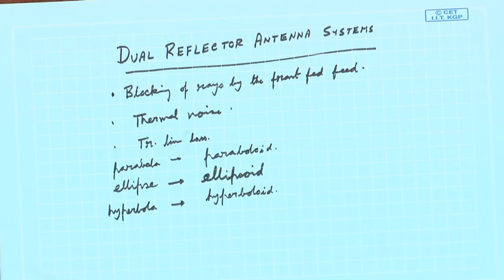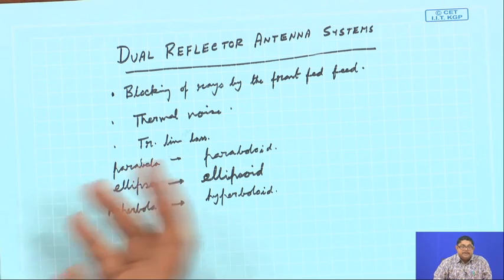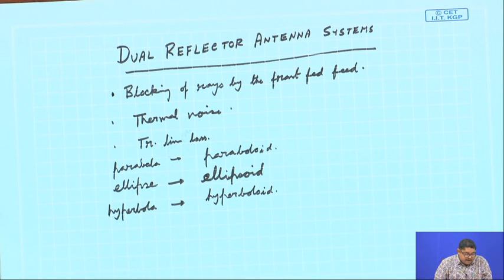Also, a modest amount of reshaping of the subreflector and the main reflector can be carried out in order to give a more uniform aperture field distribution, hence higher efficiency is obtained. By reshaping the subreflector alone, the desired effect may be obtained. Such reflectors are known as shaped reflectors.